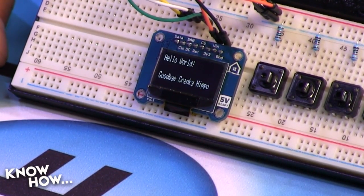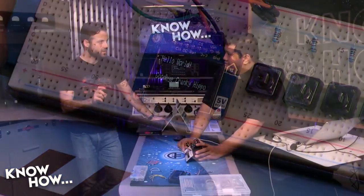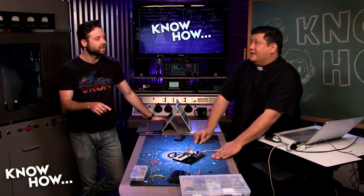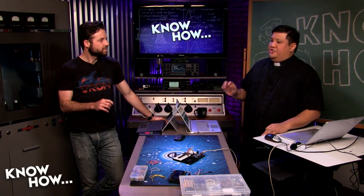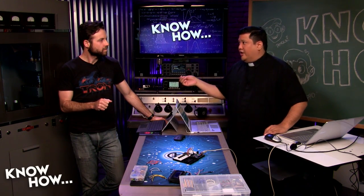Okay, but for our last project, we had to address individual digits so that they refreshed and not the whole thing. Do you have to do that for this too? Yeah, anytime you're dealing with I²C, just remember that the refresh rate isn't as high. It's not like I'm plugging a monitor into my HDMI port. So anytime you can reduce the amount of stuff that has to refresh, the better it's going to be.